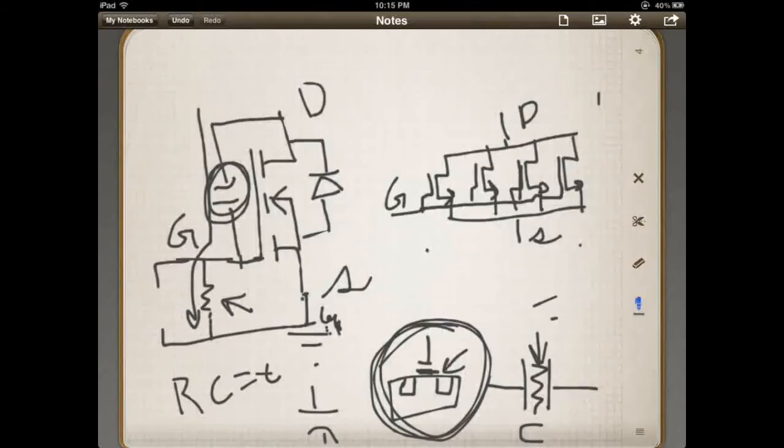Okay, well, due to paralleling all these up and the way that the silicon is constructed, it will make what's called a body diode. It'll make a little diode there that will be just inherent to how it's made. And so what that does is, you always remember that even when this is shut off in this direction, if you have this in between something in this direction, you will have a 0.7 volt drop. And to see where the 0.7 comes from, I have another video on diodes that you can watch. And that will help clear up some of that.